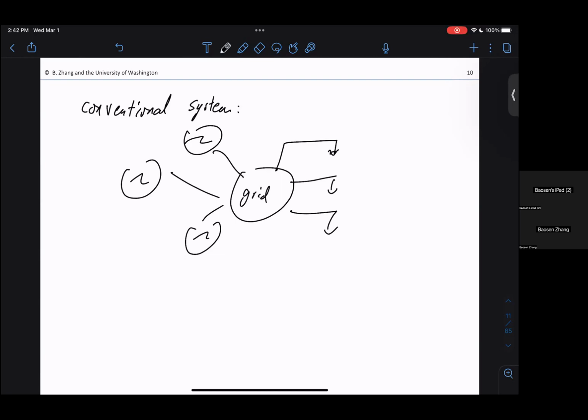There's a bunch of control problems you have to think of. Again, these generators should not fight against each other, right? If they're all measuring 60, how do you deal with the fact there will be small measurement errors at all the terminals and so on? But that's sort of, in some sense, a solved problem. You can deal with this. And the nice thing here is these are rotating machines. So it is a physical response that if the load changes, they will speed up or slow down. There's nothing you can do there. That's just how they will respond if the electric load changes in the system.